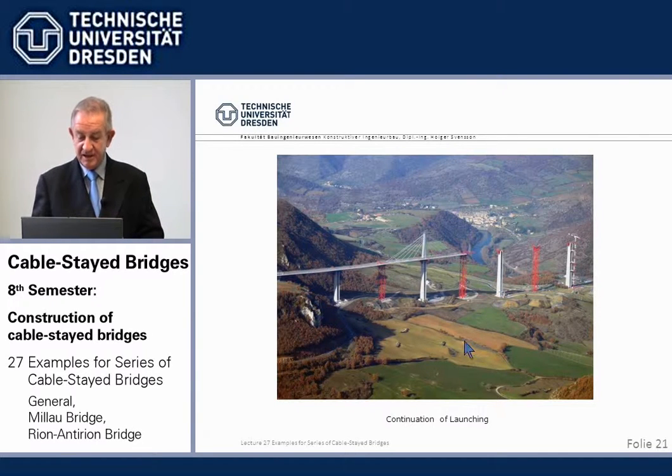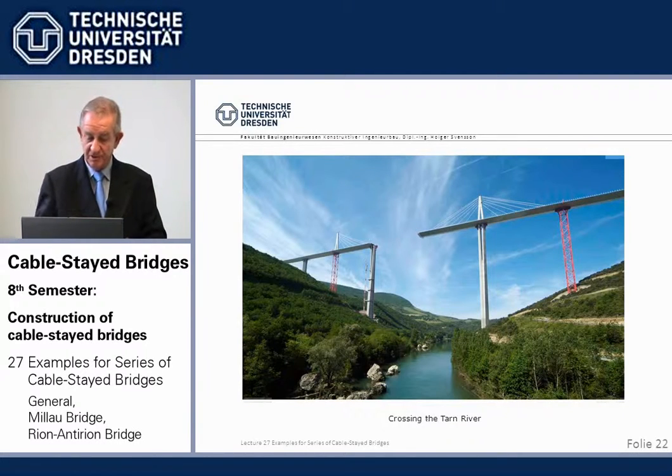And so we see here the launching in full flow. We have here in the main spans auxiliary piers. We have here the launching nose, and we have here this auxiliary tower, which here it so happens stands just on top. That's the way they launched the 1,250 meters something from each side to come to about a 2.5 kilometer long bridge.